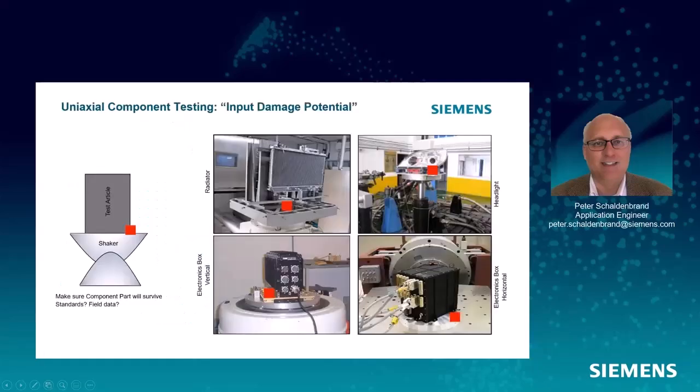Also, these shakers are single axis. We're going to develop a single axis test in 3 directions. That's just where we're at. There are some multi-axle electrodynamic shakers, but they're very rare. The common thing is single axis, and we would develop an XYZ. On the hydraulic, we see a lot more multi-axis test rigs.